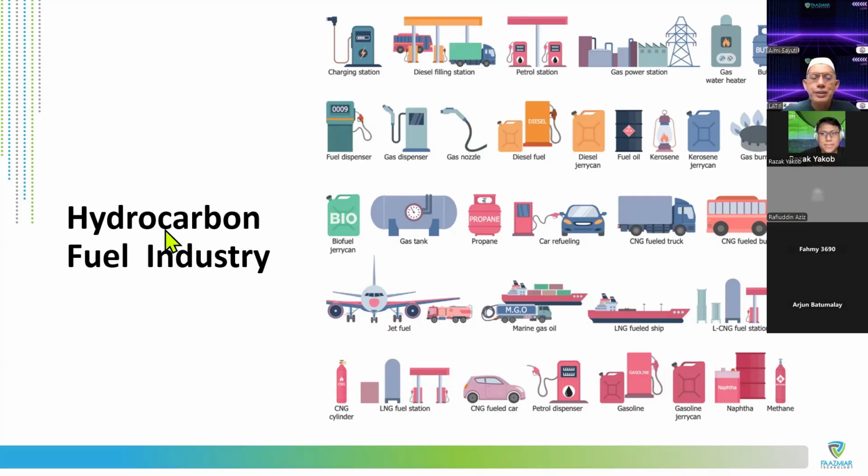But if it is gas, an FPSO normally needs a big processing facility because you have to convert most of the gas to liquid, compressed. So it's going to be quite a big facility. So normally when we talk about gas, we are always talking about pipeline rather than FPSO. So FPSO has that requirement and limitation, and of course it depends on the economics and the integrity of the well of the area.